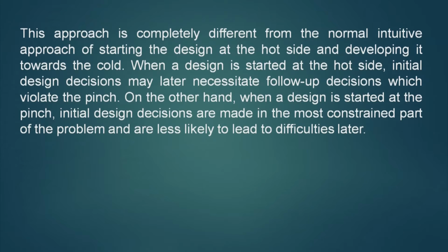On the other hand, when a design is started at the pinch, initial design decisions are made in the most constrained part of the problem and are less likely to lead to difficulties later. Based on this philosophy, the pinch design method starts from the pinch where the problem is most constricted and then moves away from the pinch.